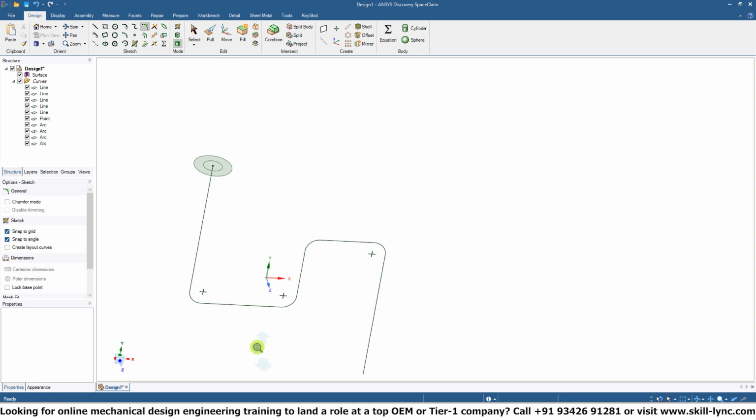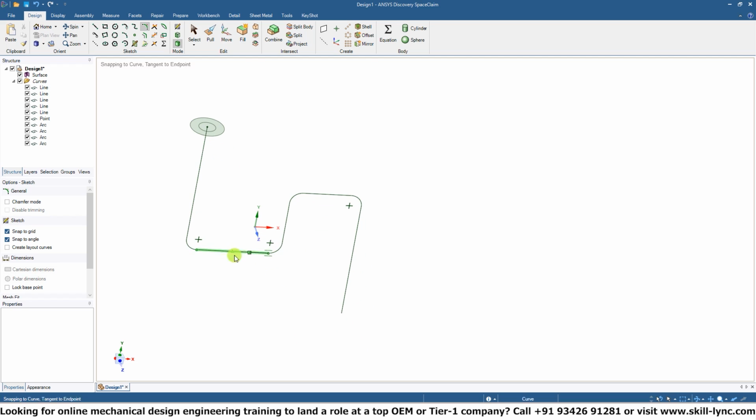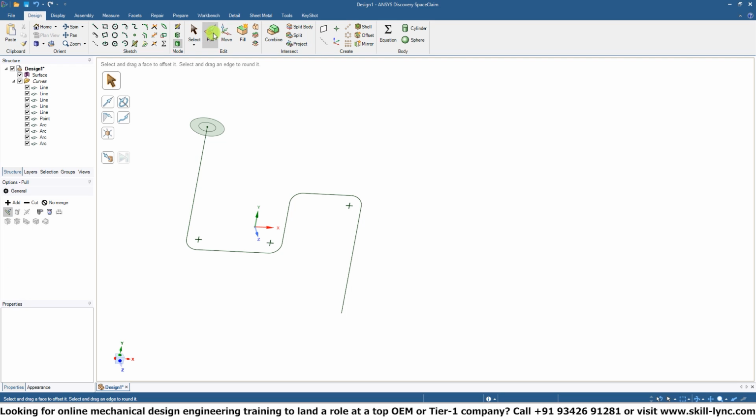Well, similarly how we did the pull options on multiple surface areas, simple pull, the cutting pull tool, we start with pull. Just click on that. And over here in these options that we have, you can see that we have a sweep option. So you can actually select first what we'd like to pull or what area.